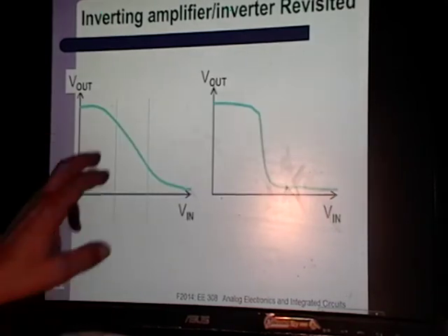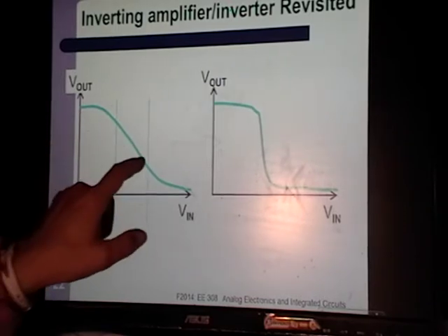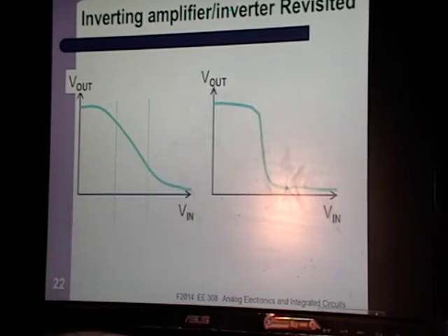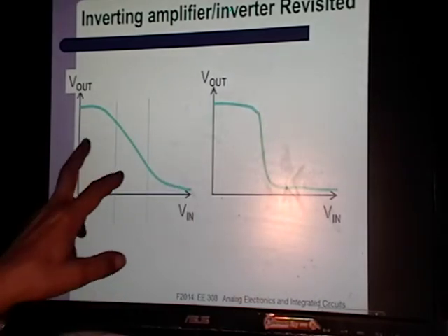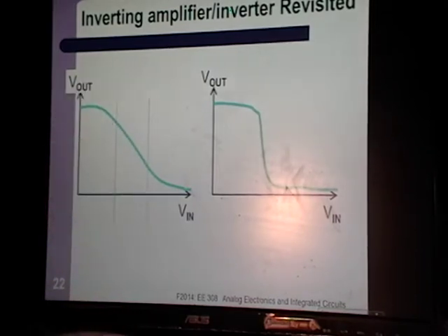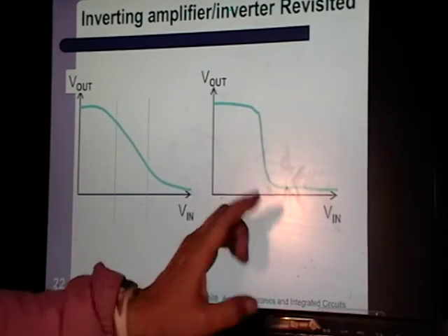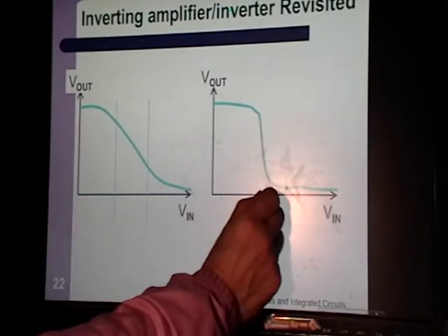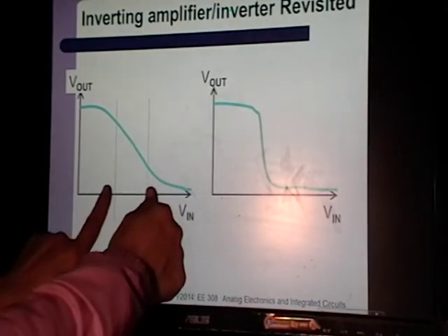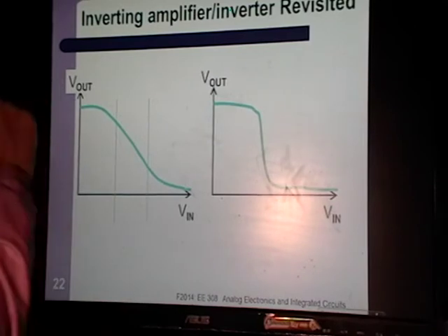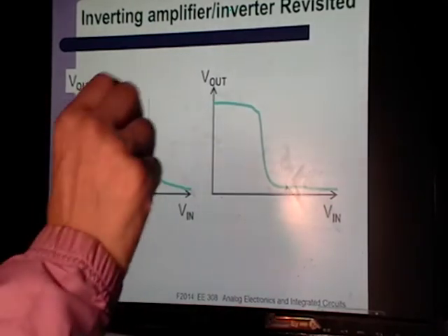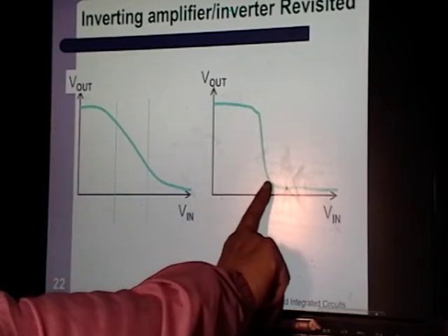Okay, this is an amplifier with not much gain. This is an amplifier with a lot of gain. If you look at these two, for us, we like a big gain because we're trying to make an op-amp, so we like this better, clearly. Now the input swing is just this wide. Over here, the input swing can be that wide. So that's something you trade off with. Bigger gain means you have to be much more careful about where your input is.